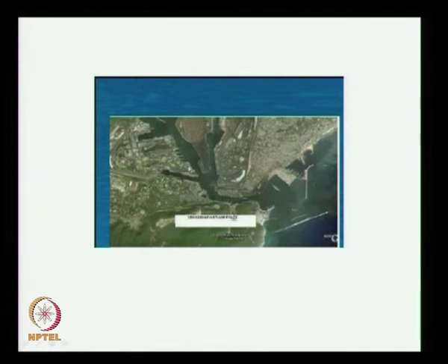This photograph shows the Visakhapatnam port. So this is the southern breakwater, this is a famous Ramakrishna beach. So one of the advantages of this particular structure is this breakwater is not starting from the shore, there is a gap between the shoreline and the breakwater, so that the sand will deposit here. They have created the sand trap inside, so that the dredger can come and work in calm environment to remove the sand, that is the advantage of this. But nowadays they are not doing this shore disconnected because it is very expensive.